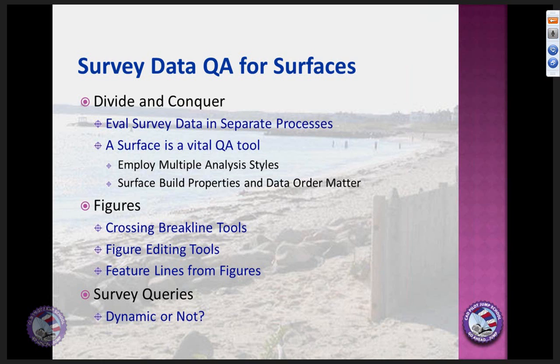No, if we got standard curb and gutter, you have to shoot back a curb or flow line or whatever you choose to shoot, and then there's a whole array of geometry around it. In Civil 3D, you can manually edit fieldbook files depending upon the data collector and your methodologies. There are a lot of ways to make a whole bunch of figures. You could also, in the office, take your figures and construct those offset geometries from your figures that way.